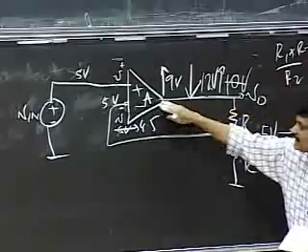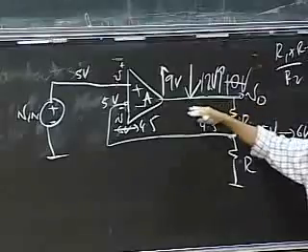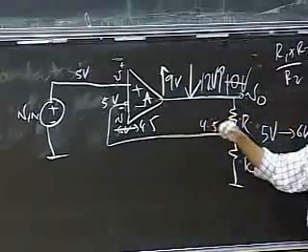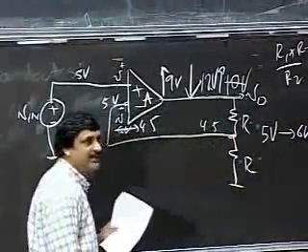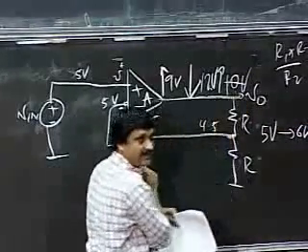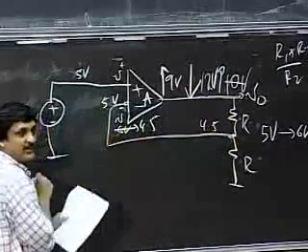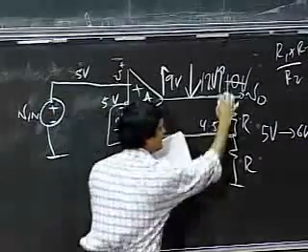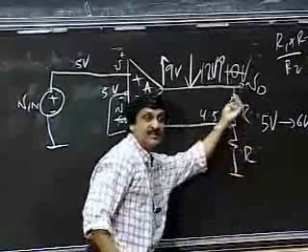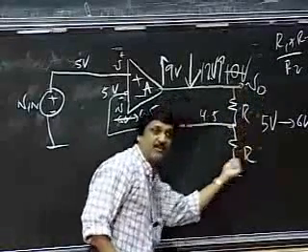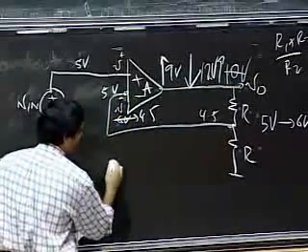So if the circuit tries not to follow the true path, the rest of the circuit tries to whack it into shape so it follows the true path. And what's happening is because I've fed back, in this arrangement, a portion of the output to the negative input. By providing this feedback of a portion of the output to the negative input, I've arranged it in a way that I have something called negative feedback.